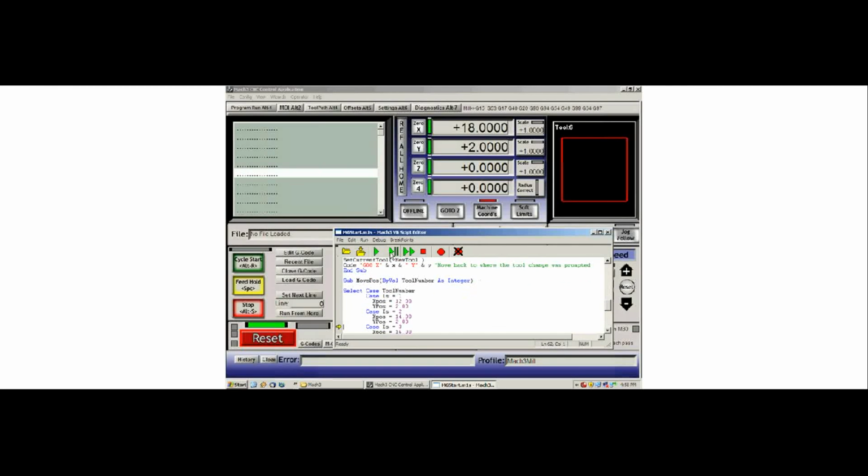and now it's looking for the next tool, and you can see it didn't actually find anything. That's because I didn't do a real tool change. It didn't pick the value out, so it went back to the same position. This won't be a problem when we actually run the script. It's because I didn't have an M6 actually activate it, but we can test to make sure that everything else is working. You can see it went back down, it paused, it deactivated the signal, pausing again.